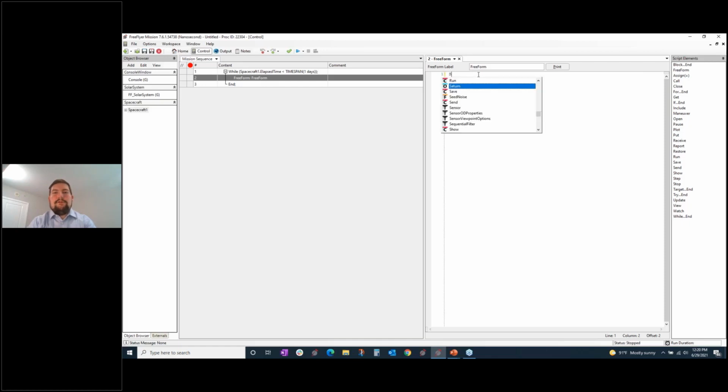So the first thing we're going to do is step the spacecraft. You can see as I'm typing that FreeFlyer autocomplete provides all the functions, properties, objects, and methods that are available for my given use case. So I'm going to step the spacecraft forward in time, and that'll step at 60 seconds. That's the step size that we set. And then at every step, I'm going to view the spacecraft in 3D. I'm going to map the spacecraft in 2D, just using simple commands here.